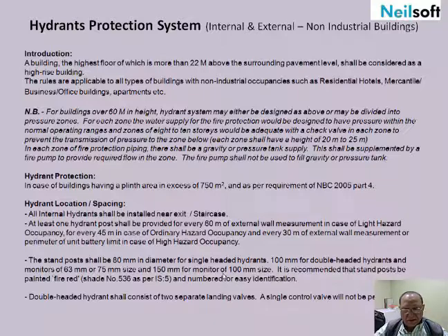What are the monitors? We had discussed earlier also, here also we say, as per the code requirement, the hydrant must be placed within 15 meters of the periphery of the building outline. If it is exceeding more than that, it must be provided with the monitors.